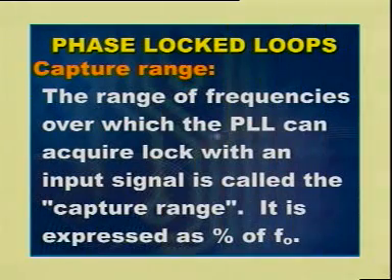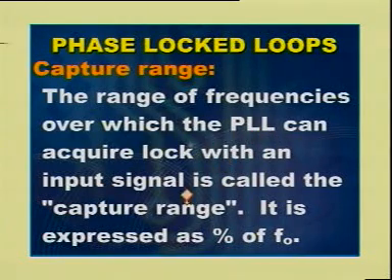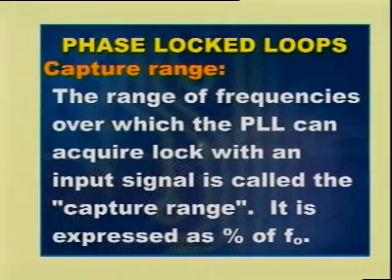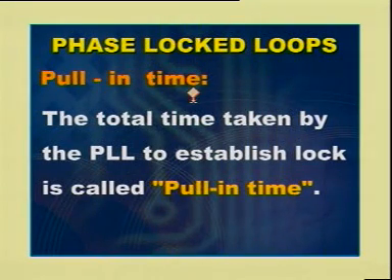Capture range, the range of frequencies over which the PLL can acquire lock with the input signal is called the capture range. It is expressed as percentage of F0. Pull-in time, the total time taken by the PLL to establish lock is called pull-in time.